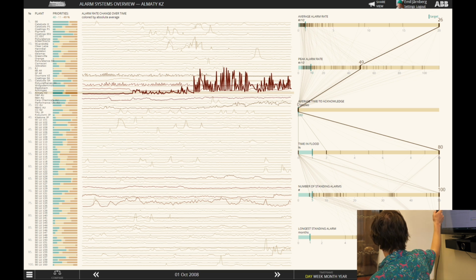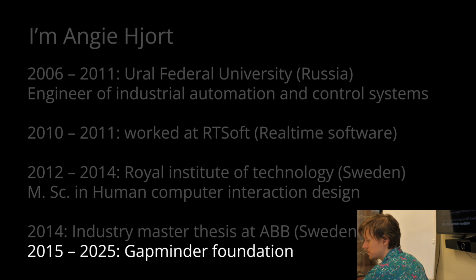These alarms are problematic because usually the operator would get a flood of them, like hundreds, and then, what do I do now? And then there's the overwhelming stream of information to the operator, and the operator is not able to do anything more with that. So analyzing them and bringing down the number of alarms is considered a useful thing, but a hard thing because can I really remove alarms? It's a bit of a legal and technological, legal and other kind of considerations.